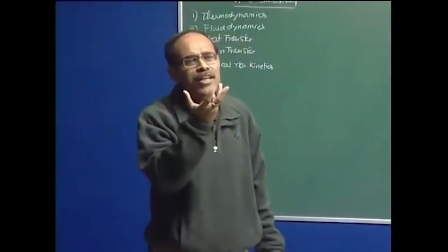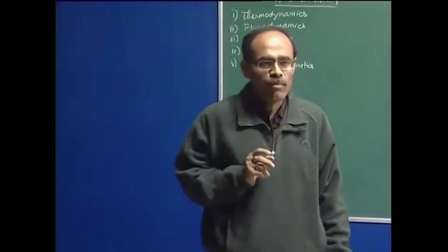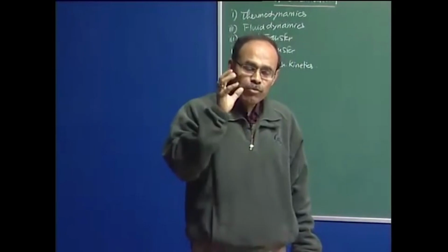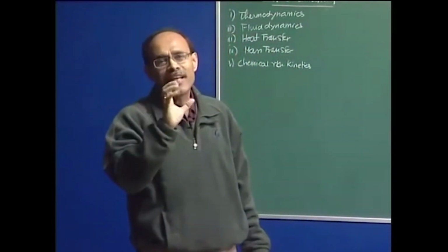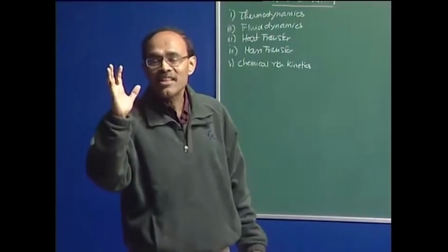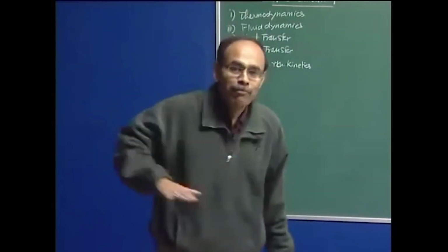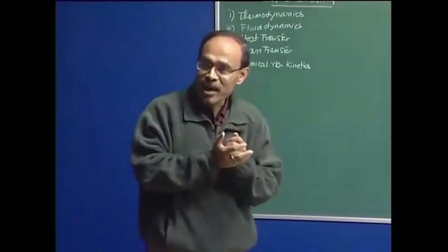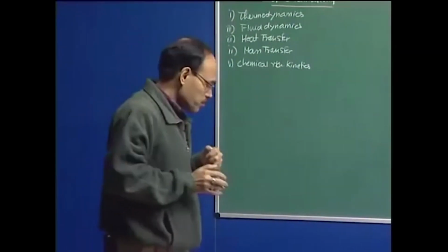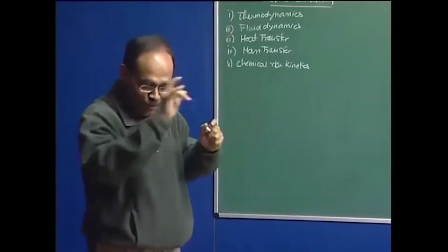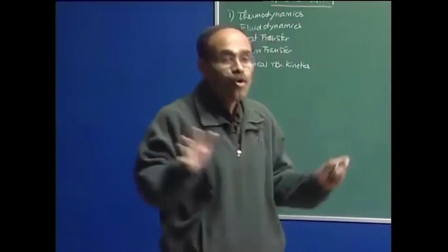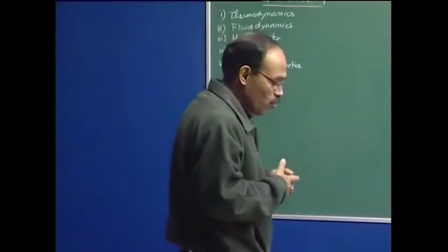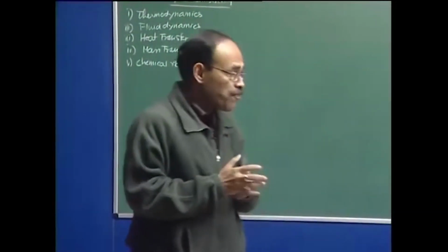So, simplification and idealization in terms of dimensionality of the problem is not going to be very much advantageous in our case, and we will find that the flows in majority of the cases are going to be three dimensional in nature. Pipe flow type problems or flow over a flat plate type problems, these classical flow problems will never be encountered under steel making situation. Particularly if you look at the processes starting from BOF to the continuous casting, nowhere approximation of a two dimensional flow or a one dimensional flow will be tenable.